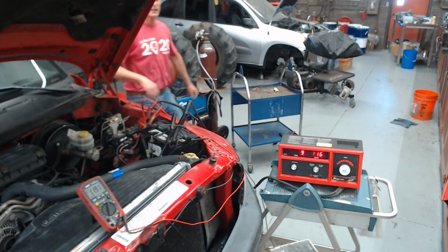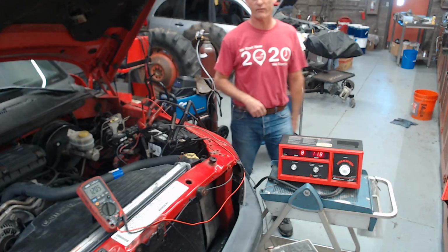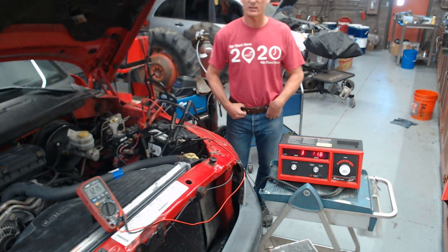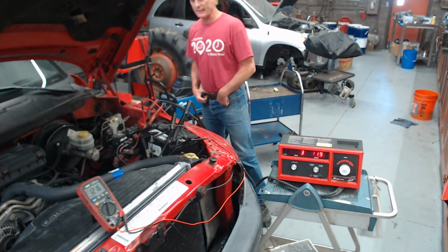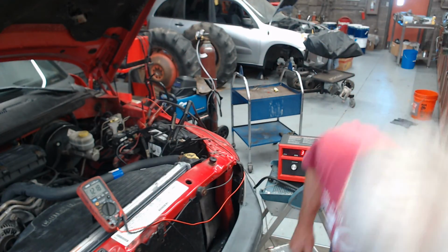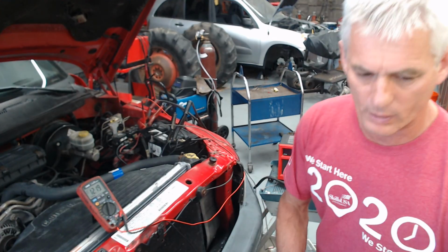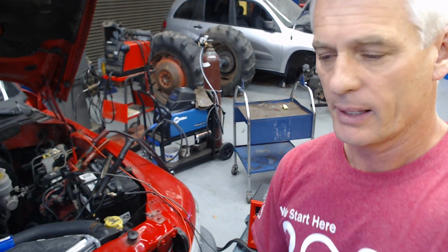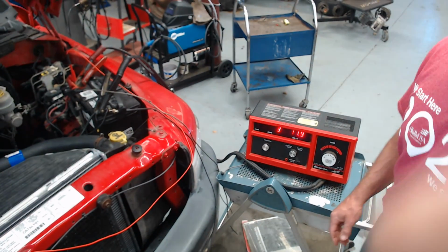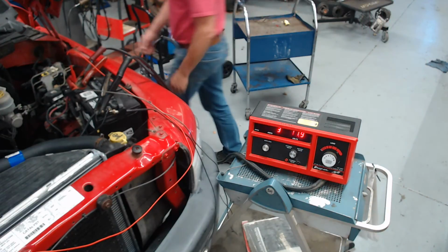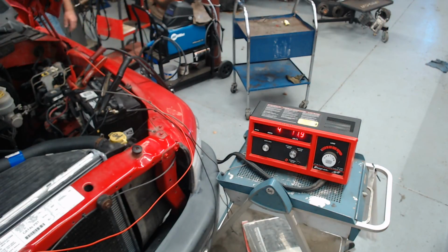So I think I saw from the cab, it was a little hard for me to see, about 10.4 volts and about 160 amps. I'll see if I can get in a little bit better position by pulling the camera closer, and we'll give it one more shot. So we'll just come really, really close, and we'll point that camera down. So you're going to be looking right here. Now notice the resting voltage is down from all that cranking. So here we go. Let's see what we get this time.